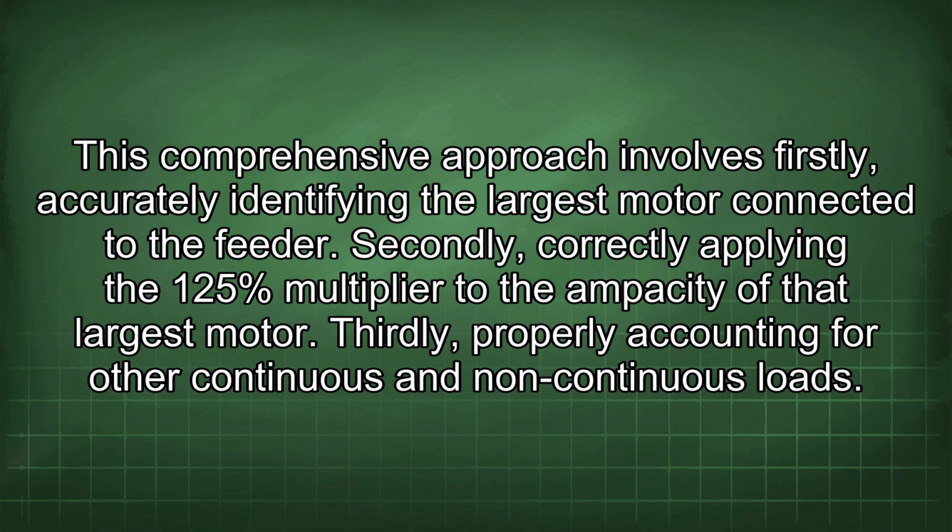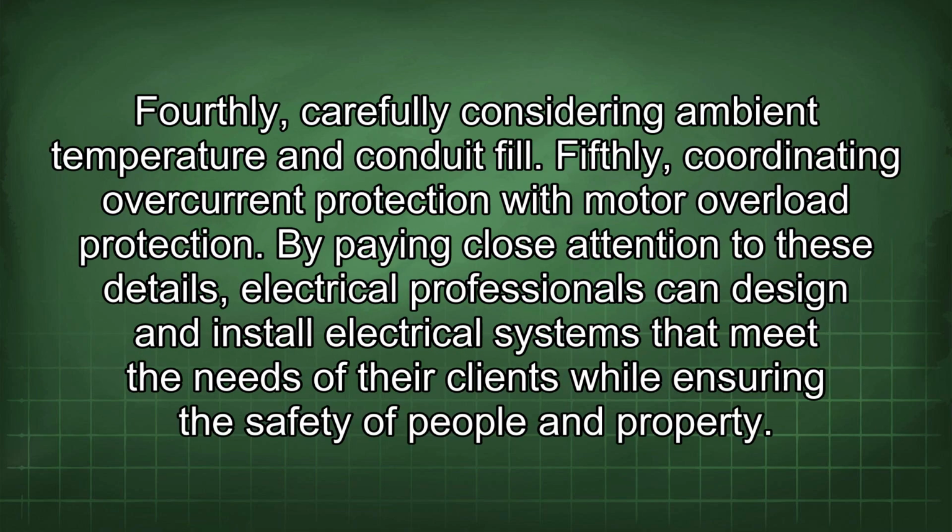Secondly, correctly applying the 125% multiplier to the ampacity of that largest motor. Thirdly, properly accounting for other continuous and non-continuous loads. Fourthly, carefully considering ambient temperature and conduit fill. Fifthly, coordinating overcurrent protection with motor overload protection. By paying close attention to these details, electrical professionals can design and install electrical systems that meet the needs of their clients while ensuring the safety of people and property.